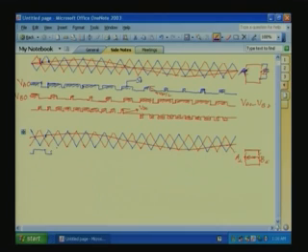So, if you repeat for other triangles also, you will get this pattern, but here the height is VDC by 2, and it will go plus VDC by 2 and minus VDC by 2. So, this is the pole voltage waveform of the second converter with a 90-degree phase shifted triangle with respect to the same leg of converter 1, that is this converter.